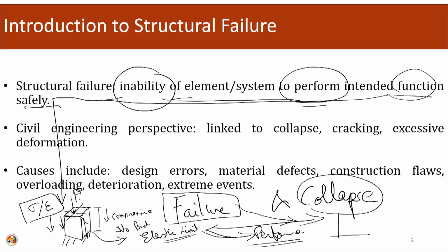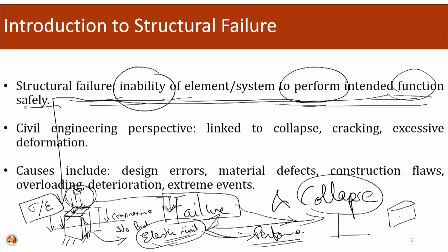It can still take increased loading. The only thing that is going to happen is that the section will then be in the elastoplastic or the plastic regime. The elastic regime has been exceeded. So, the functional performance which I have set as an elastic limit has been exceeded. It means that the section can no longer safely hold the load within the elastic limit. This is called the failure of the section. It does not mean that the entire section has crushed and collapse has occurred.